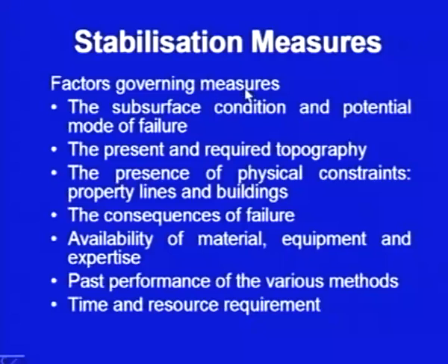These are the factors which will govern these measures: the subsurface condition and potential mode of failure. What is the kind of failure you are going to have, whether it is planar or circular. Secondly, the present and required topography. If we want to make it stable and we want to change the topography, we have to consider how much area it really needs and so on.